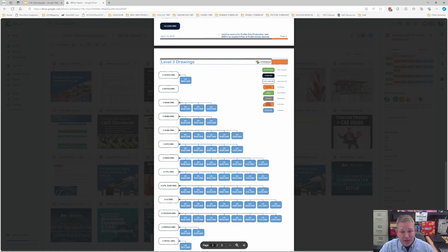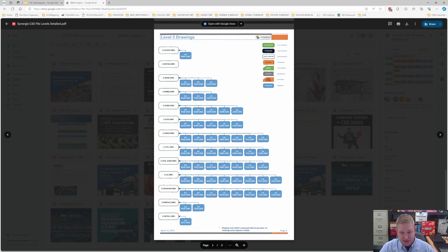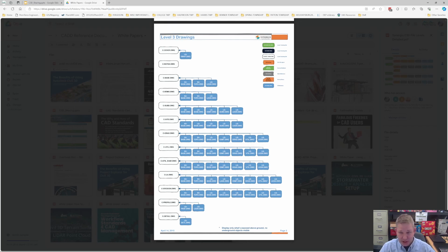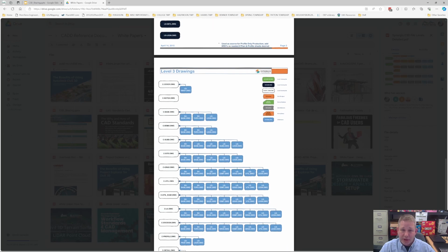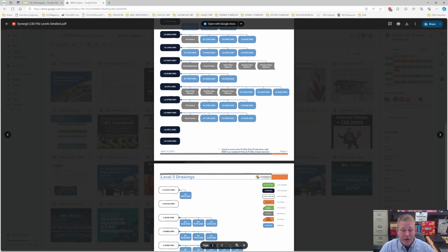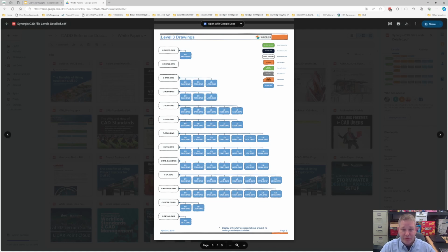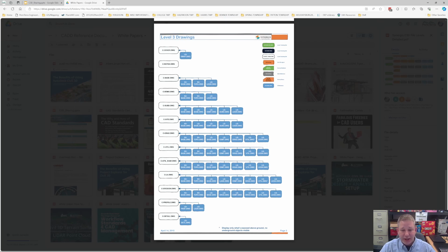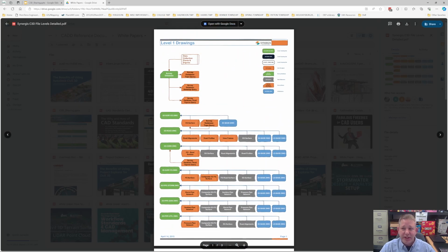And then the level 3 is more of your plot sheets and such, bringing all that information together, either via XREF, or, well, in this case it shows all XREFs, but you could also possibly do data references. So this system can get very confusing very quickly. We may not be at this type of level of discussion yet, but we're at a good place to start testing it out, seeing how it works, and going from there.